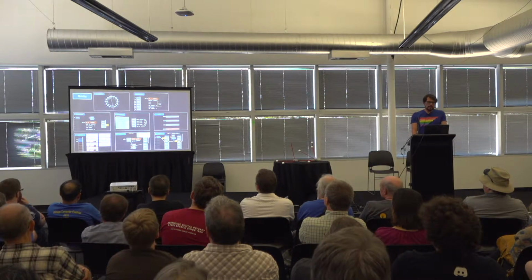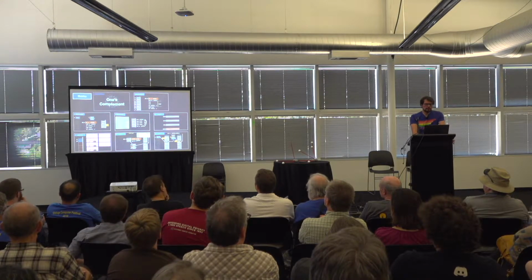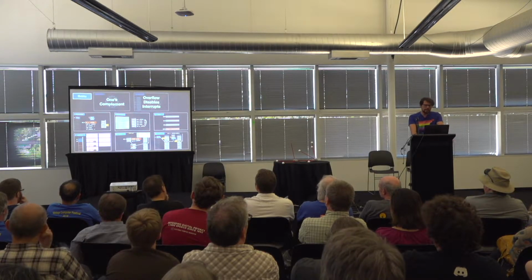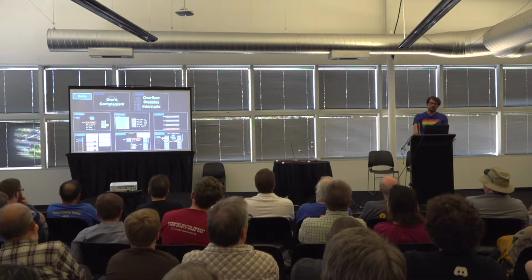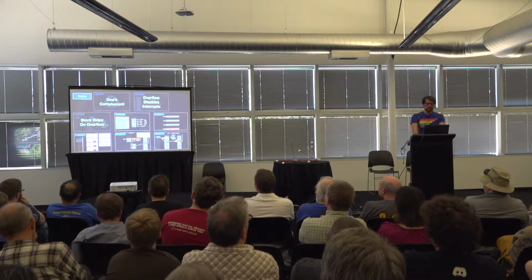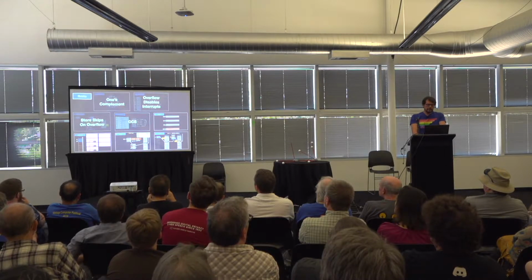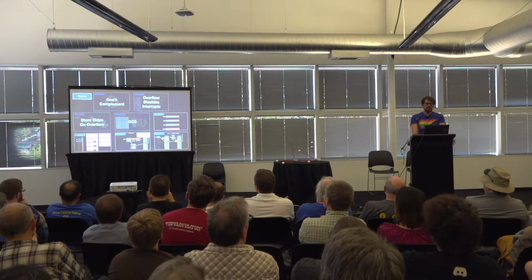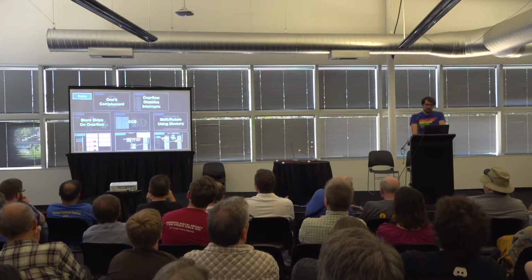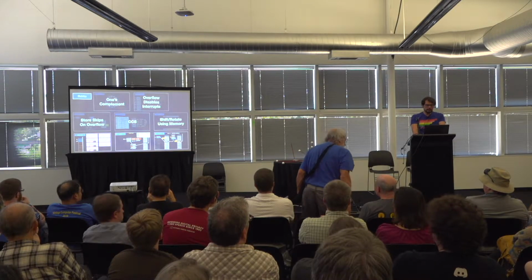Looking at the instruction set architecture as a whole, there are many quirky and unusual features when compared to modern architectures. It uses 1's complement encoding instead of 2's complement. It has no status register. The overflow flag cannot be saved, so interrupts are disabled until overflow is resolved. The store instruction may skip a word under certain circumstances. The CCS instruction can skip several words and can be outright dangerous if the instruction following it uses prefixes. There are no shift or rotate instructions, but magic memory locations that shift and rotate when writing into them.